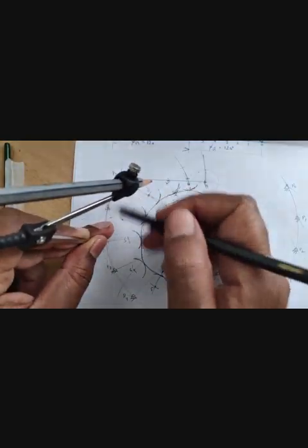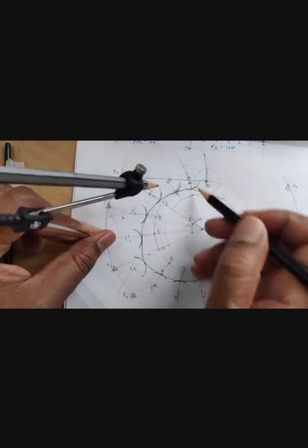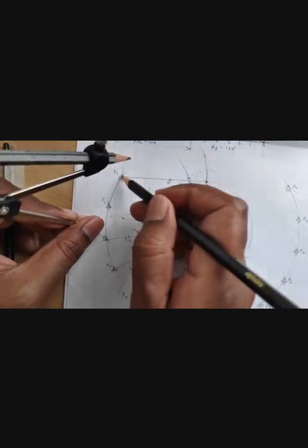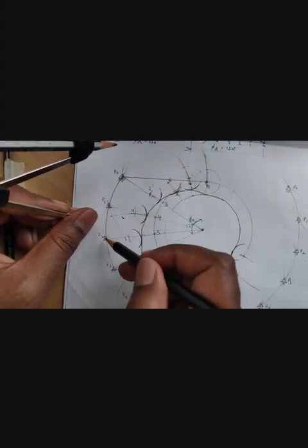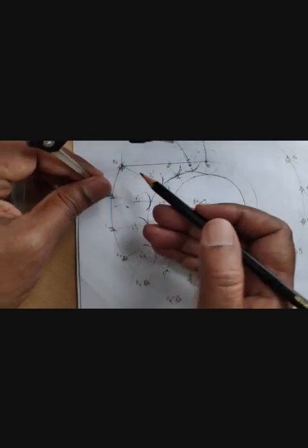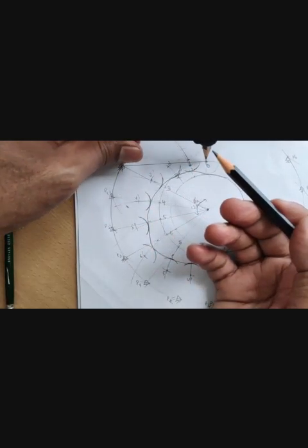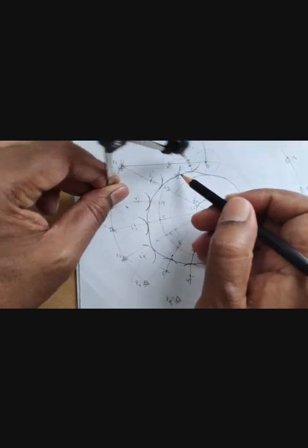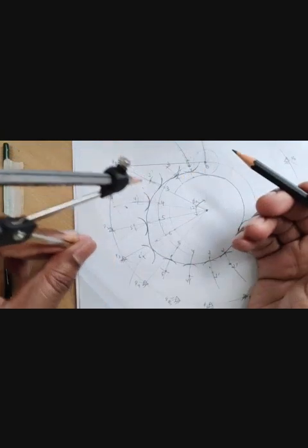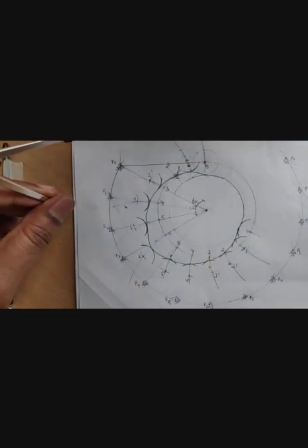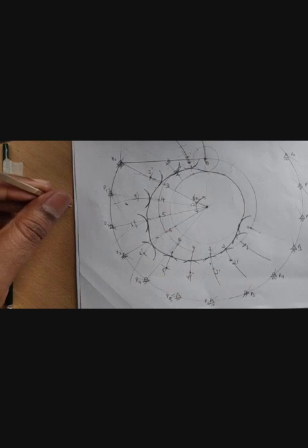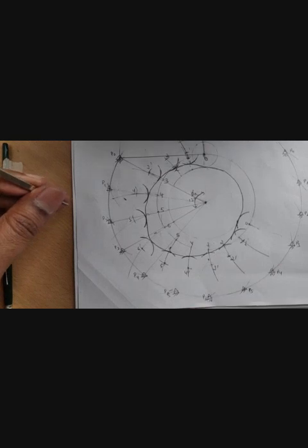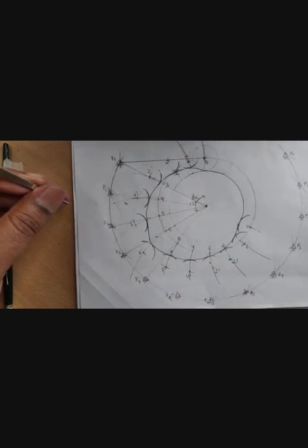So first locate these points, and then instead of actually locating 1, 2, 3, 4, you can locate these angles as P1, P2 at 20, 40, 60, like this. Then since the lever length is known, you can start drawing it here. Where it starts at the prime circle, there you can mark it as 1. From here you can mark it as 2, and that actually saves almost 3 to 4 minutes. So I should have actually done it that way to save a lot of time. I will post one more video which would teach you to solve it in that way.